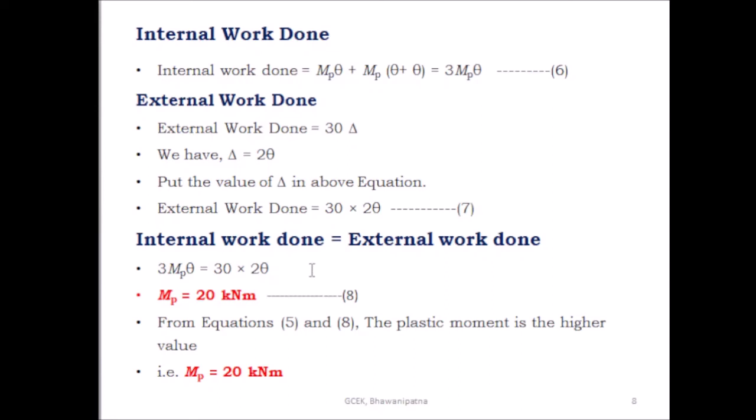Then equate internal work done with the external work done. Here you know the internal work done is equal to 3 Mp theta, and the external work done is equal to 30 into 2 theta. Then after simplification, the plastic moment is equal to 20 kilonewton meter.